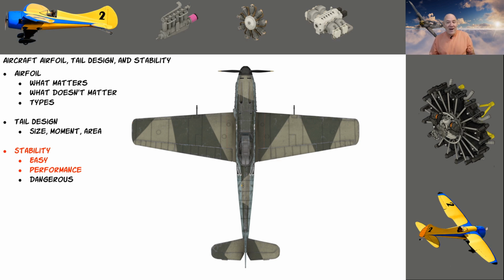Most of us would never have that much pitch up relative to the way we're going. When you come out of a loop, though, sometimes, if you're not coming onto the power and you're keeping the power back and then it snap rolls and crashes, everybody goes, hey, my radio took a crap. You stalled the airplane. You can stall a plane at any speed.